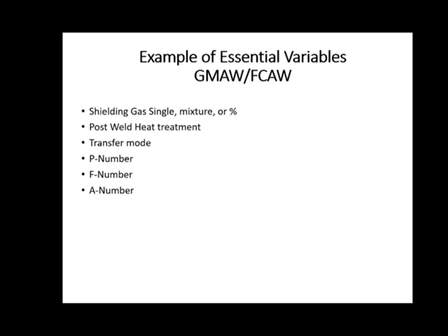Let's say we qualify a weld procedure with no post-weld heat treatment, and then for some reason we're going to need one that needs post-weld heat treatment. Well, if you go either way, from having post-weld heat treatment to no post-weld heat treatment, or the other way around, you need to requalify.